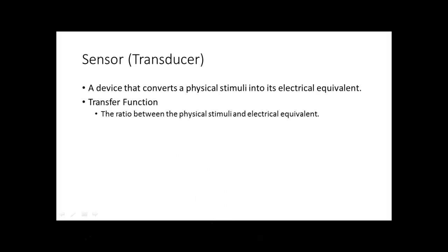Transducer is just another term, a device. You'll hear people call sensors transducers. A transducer is anything that takes energy in one form and converts it over to another form. So a sensor is a transducer, but a transducer does not have to be a sensor.